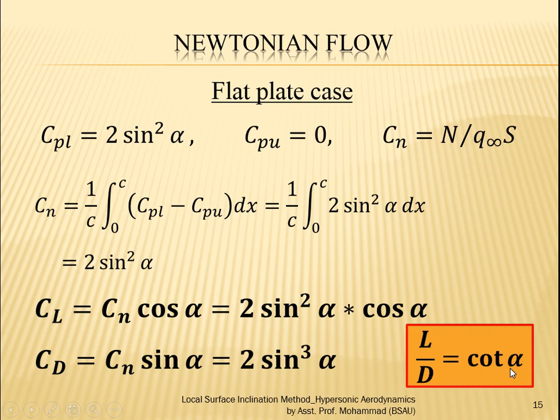One thing we have to be careful to remember: these lift and drag relations depend upon Newtonian flow, or Newton's sine squared law. But this lift to drag ratio is free of that. It's always valid because it does not depend upon the inclination method, just upon the angle of attack. Actually, this alpha is not the angle of attack, it is the deflection angle.